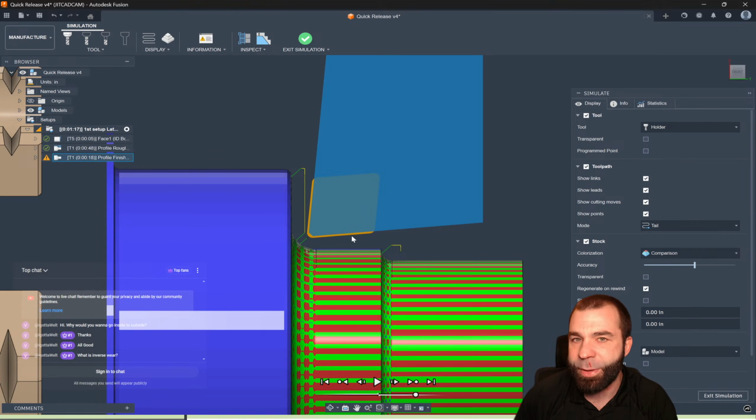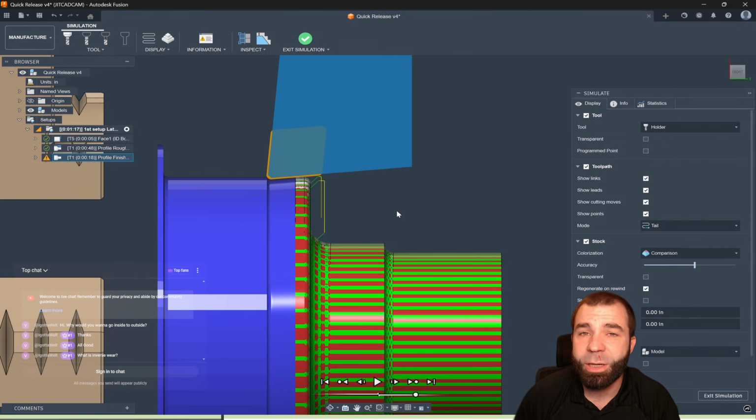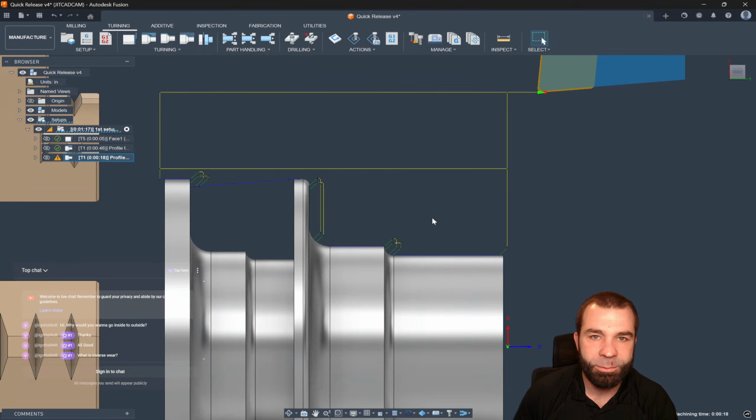I'm also not back dragging necessarily in the X direction or the Z direction on the back side of the insert. So again, very important when you guys are trying to get some good surface finishes. That back dragging can cause some problems if you're trying to take too much material at once, because you're engaging a large amount of the surface of the cutter.